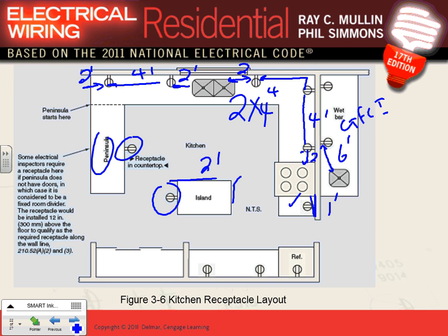Any question, guys, about laying out the receptacle? Now, Aaron, these are guidelines. You don't want to go minimum. Don't go splitting hairs and measure exactly. So if you have to add another receptacle, do it. Now remember, we're designers and engineers, guys. We don't go by the minimum, right? But what I hate to see is putting 5 receptacles in this little area here. You don't want to overkill.